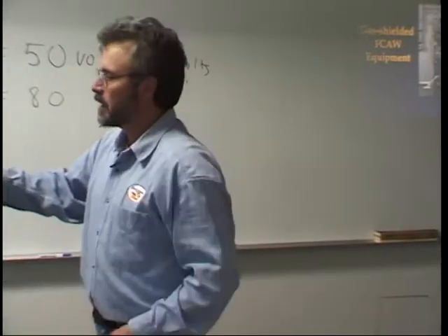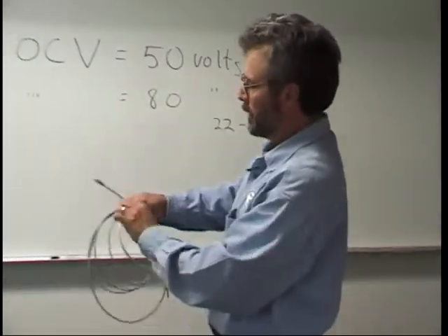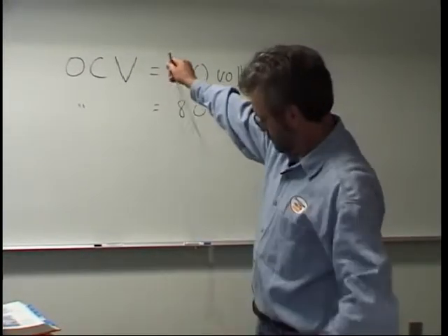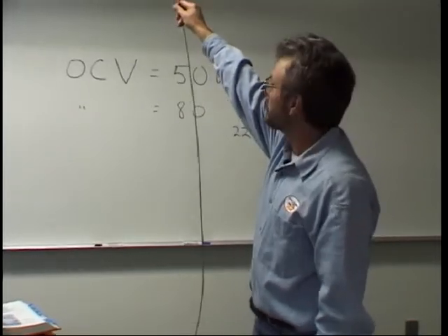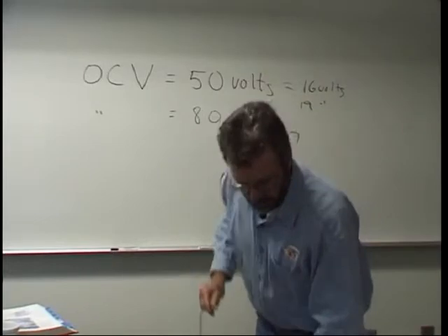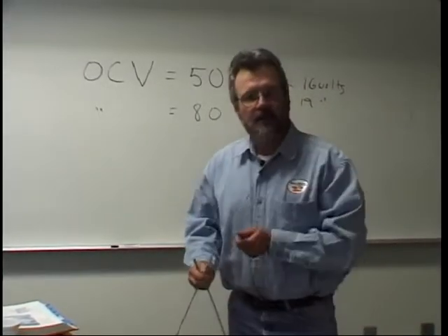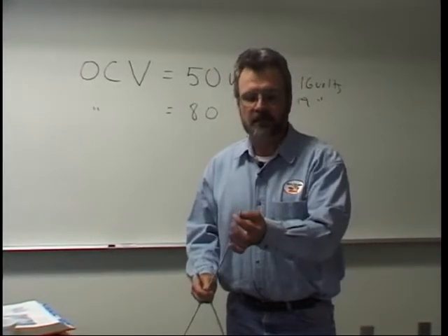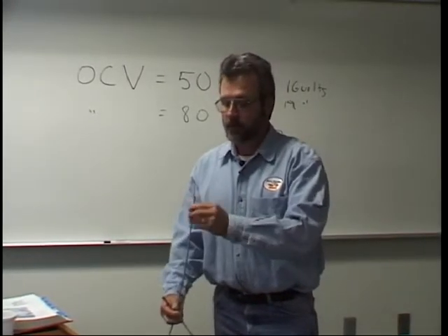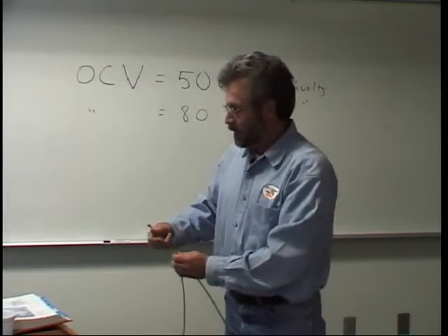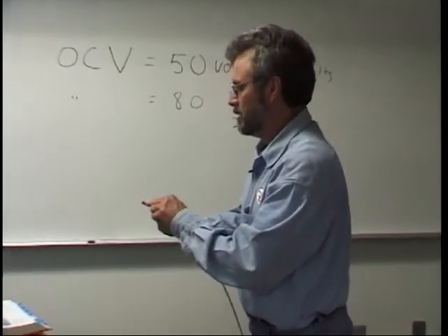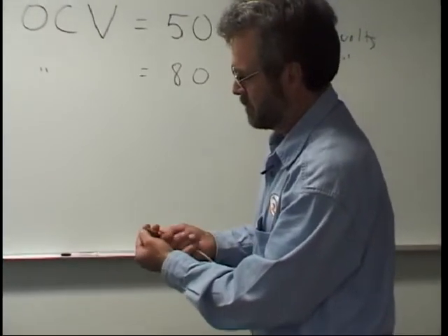I always thought they kind of looked like brake cables off of a car, and they do kind of. And there you can see it just uncoils just like that. Your wire is fed in here, and then you simply feed this thing down the gun until it comes out the end, and you cut off any excess that you have. And the wire, of course, goes down through the middle of it. Now you can tell the size by reading right here. It'll be stamped in right here at the end.